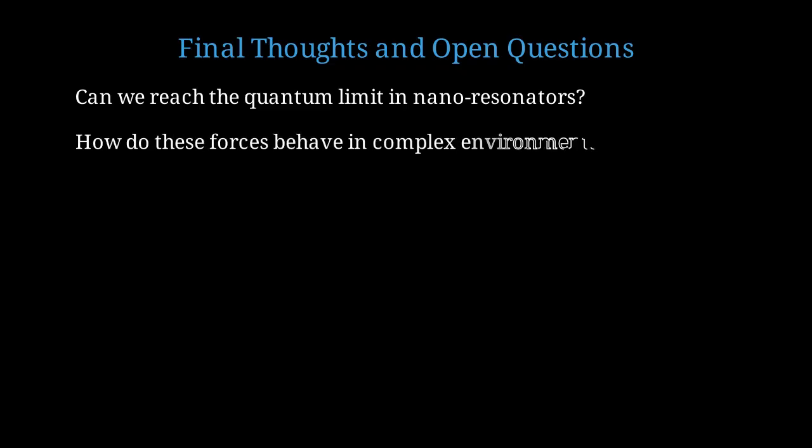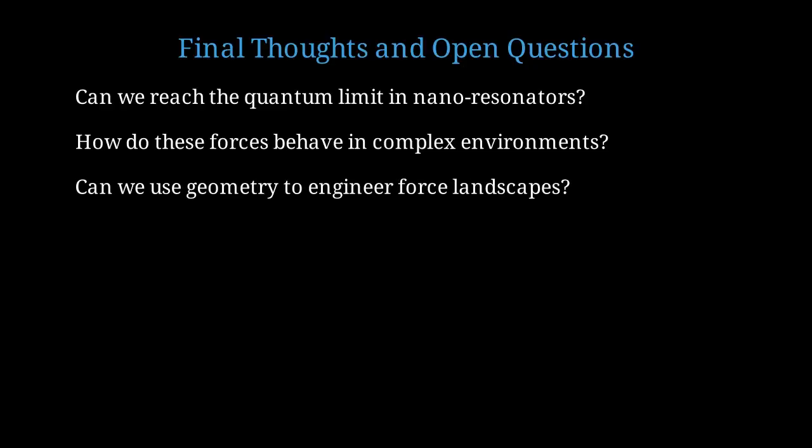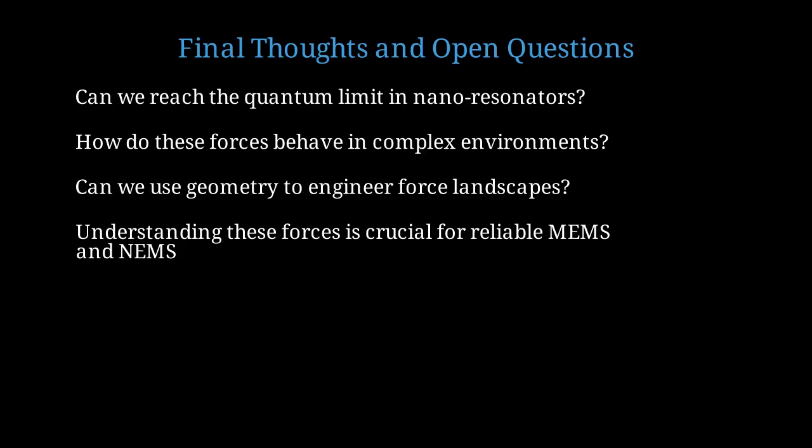How do these forces behave in complex environments like liquids or ionic solutions? This is important for bio, MEMS, and lab-on-chip applications. Can we engineer the geometry and materials to create custom force landscapes? This could enable new types of self-assembly or reconfigurable nanodevices. Understanding van der Waals and Casimir forces is absolutely crucial for designing reliable MEMS and NEMS devices. As we continue to push to smaller scales, these quantum mechanical effects will only become more important and more interesting.